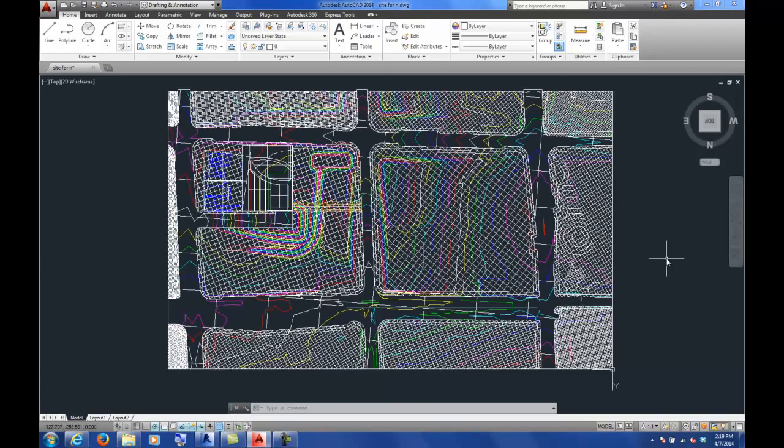One thing that's key about working in topography and using topography drawings such as this, which would be like a survey drawing, where it looks like somebody probably recreated this by tracing some kind of map file that had contours and then had that as an underlay in DWG format and traced it, because it looks like each of the contours are their own individual layer. So this one happens to be 734, which I would assume is the contour line 734. The next one over, we're down to 733 and so on. So we've got 1 foot contours shown on here.